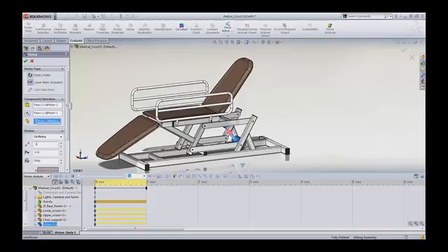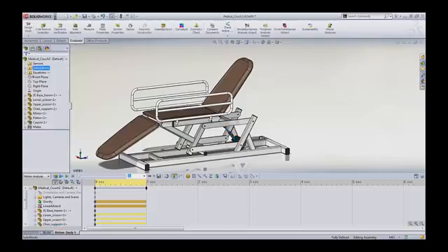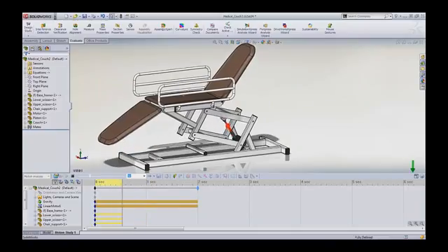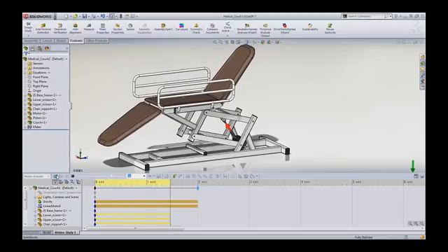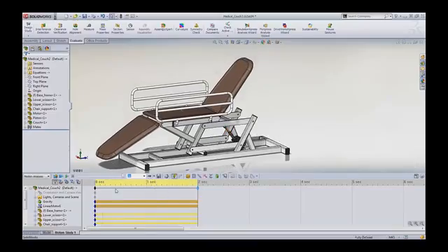Which kind of integration is with SOLIDWORKS? So we have the same user interface. We are just adding a motor, a linear motor, to the bottom of the mechanism, and we are using an oscillating device. So in this case, with the oscillating device, we can just calculate the kinematics simulation. We can see if it's working and which is the extent of the leverages. Of course, later on we will see the results.